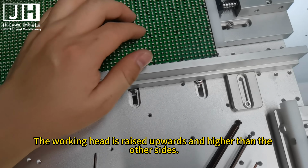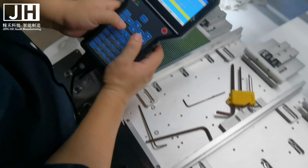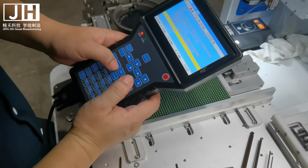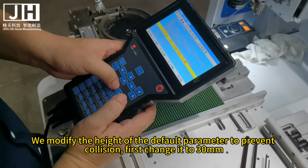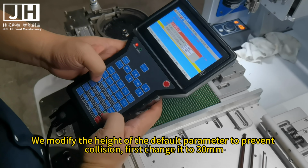The working head is raised upwards and higher than the other sides. We modify the height of the default parameter to prevent collision. First change it to 30 millimeters.